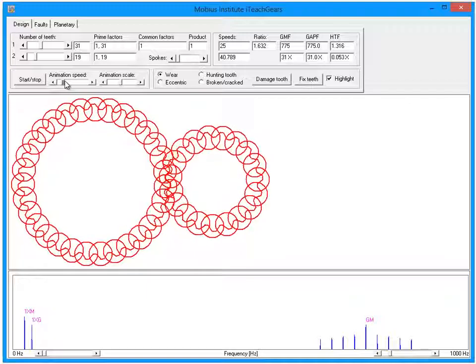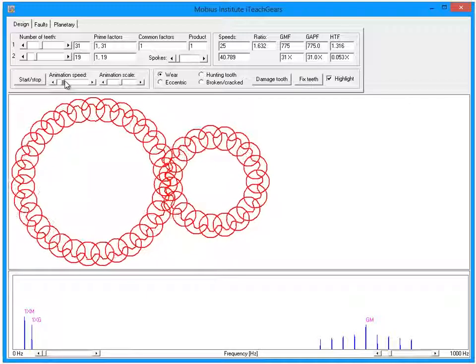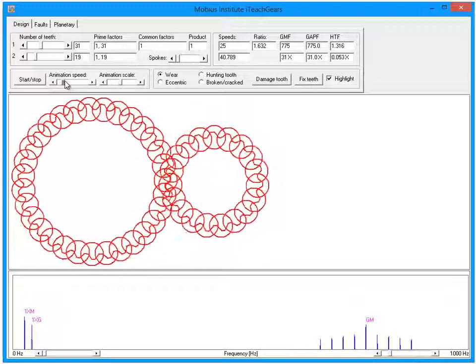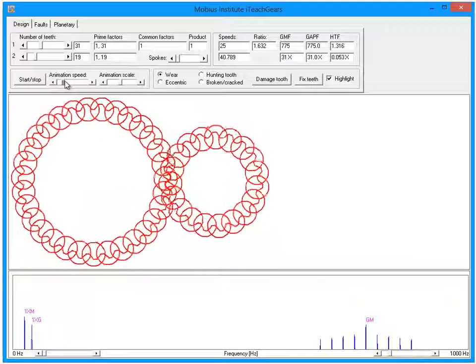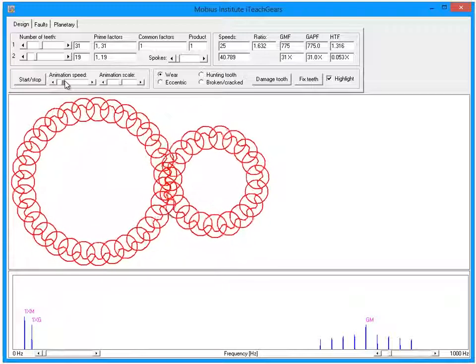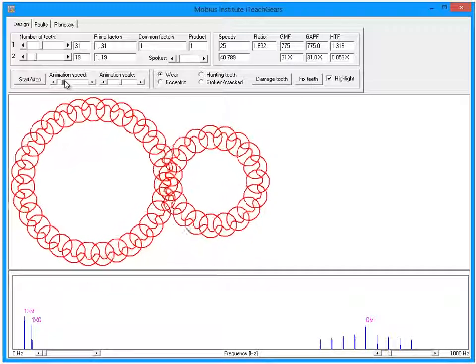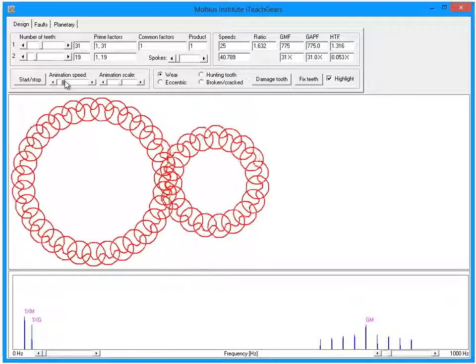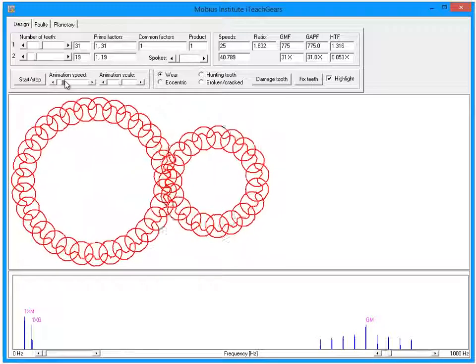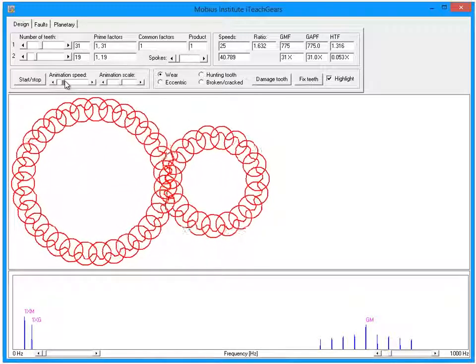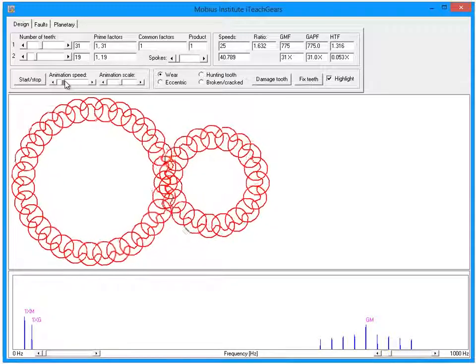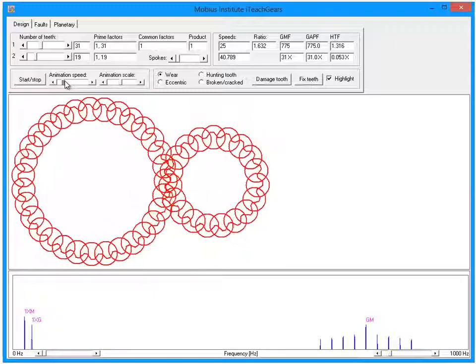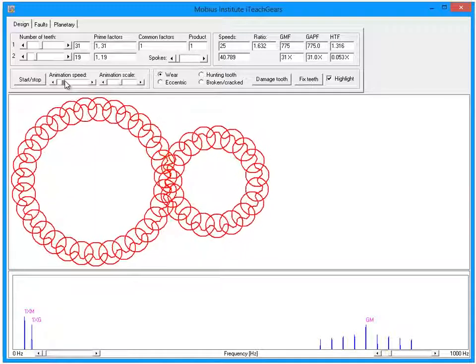And as you can imagine, these gears are just turning, and so this is just repeating. The same could be true if, when the gearbox was transported or installed, two mating teeth damage each other, and as the gearbox rotates, that damage, that imperfection, has the potential to spread around all the gears.